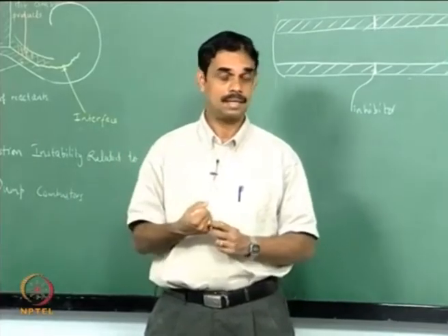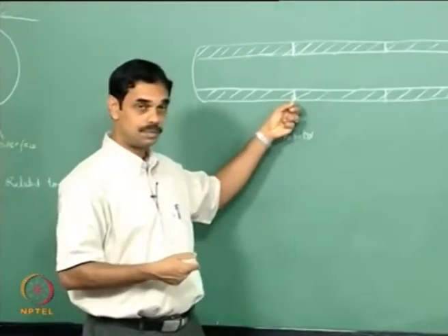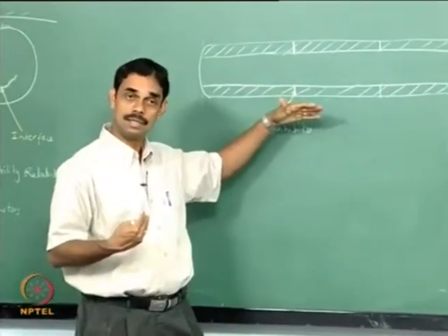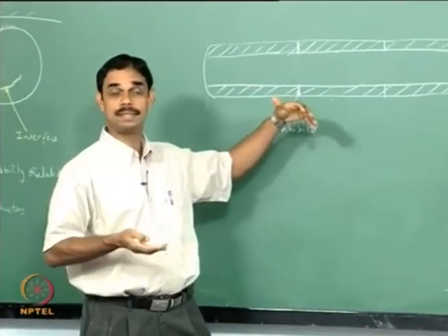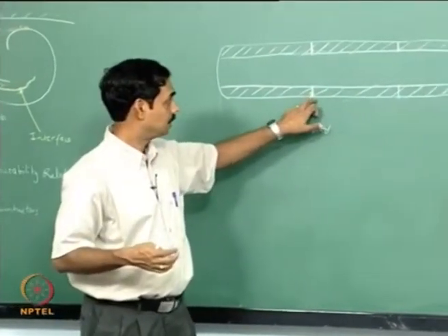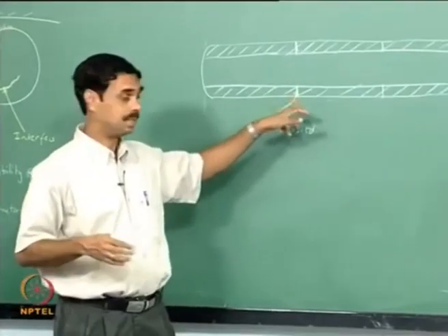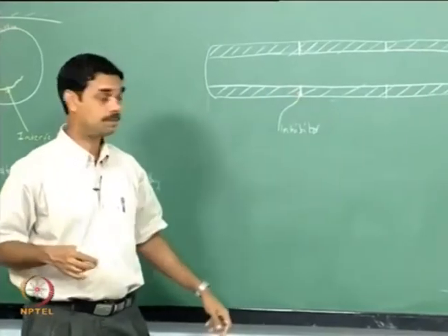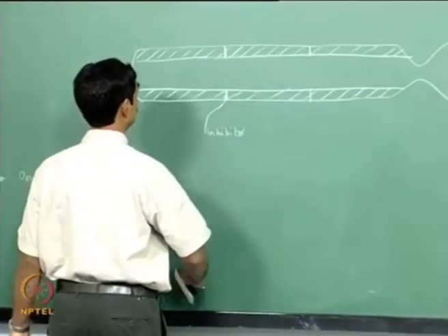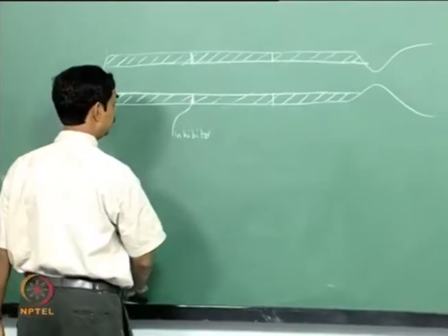In a solid rocket, the propellant itself is insulating the outer casing structure, as we saw last semester in propulsion class. So we want the propellant there, we do not want the gases to burn and come in contact with the wall. So we put this inhibitor, and after some time these inhibitors will protrude out.